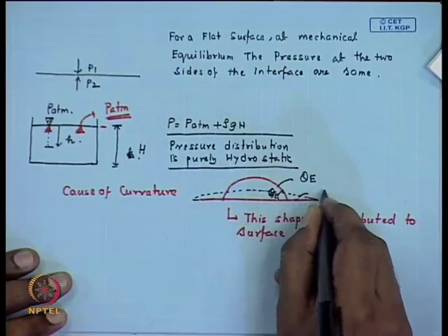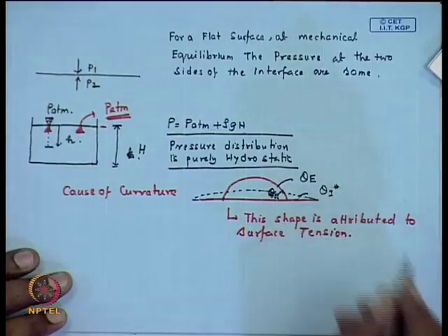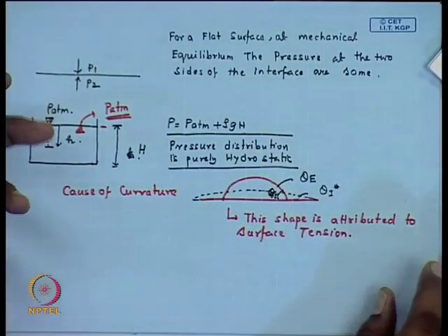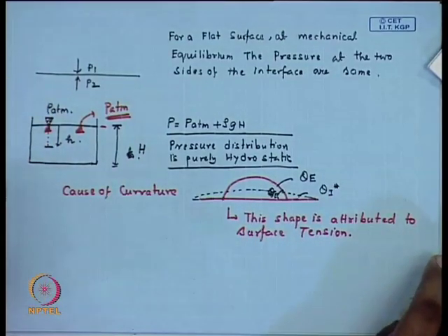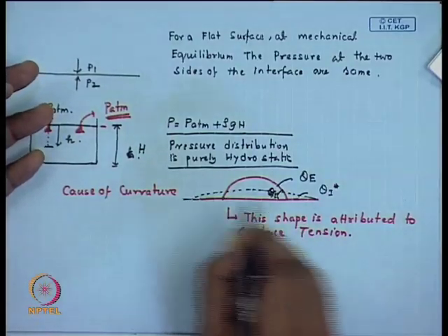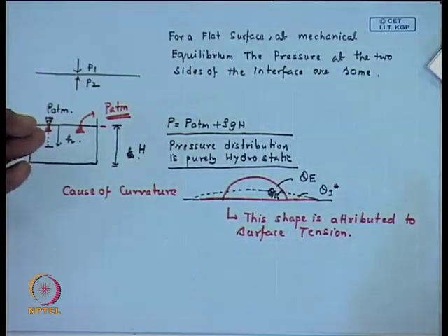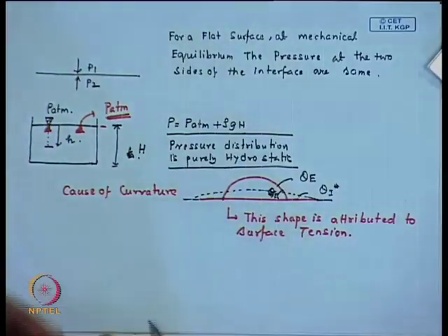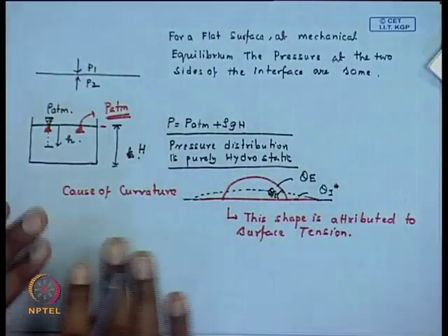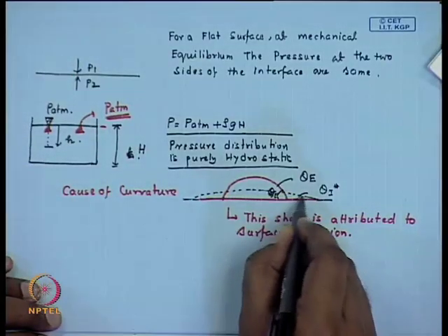So, this intrinsic contact angle is lower than the equilibrium contact angle, or in other words there is now an imbalance in the horizontal component of the surface and interfacial tension. So, the liquid retracts back till it attains theta e, the equilibrium contact angle is attained back. But the other way to look into this problem is that by spreading you have actually created more surface area for this liquid drop.